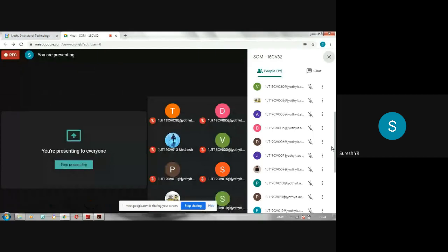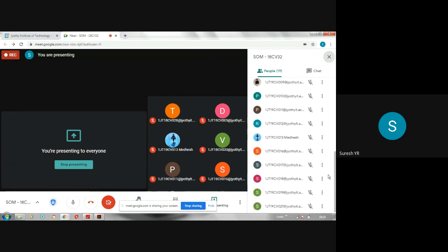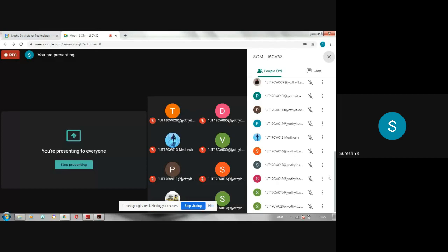If it is fixed condition, the column is strong. Based on the end condition of the column, whether it is hinged or fixed, both ends hinged or both ends fixed, one of the 4 conditions will be given. So based on that, we have to decide the value of L.